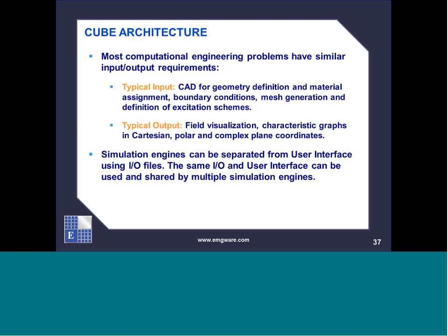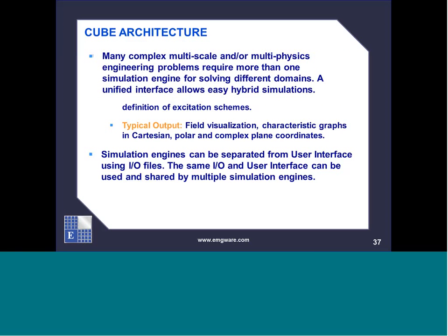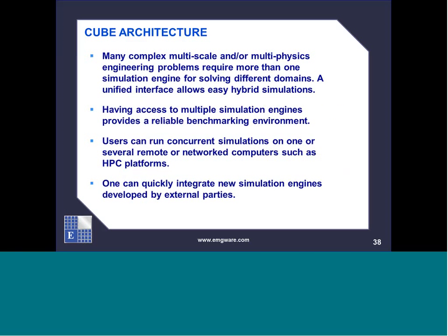So what we did in EM.Cube was provide a common, unified, streamlined user interface for all these different simulation engines or numerical techniques. You can import or build your structure from scratch in the same CAD environment, and then depending on what is the right numerical technique for it, you can use a certain simulation engine and a certain computational module for it.